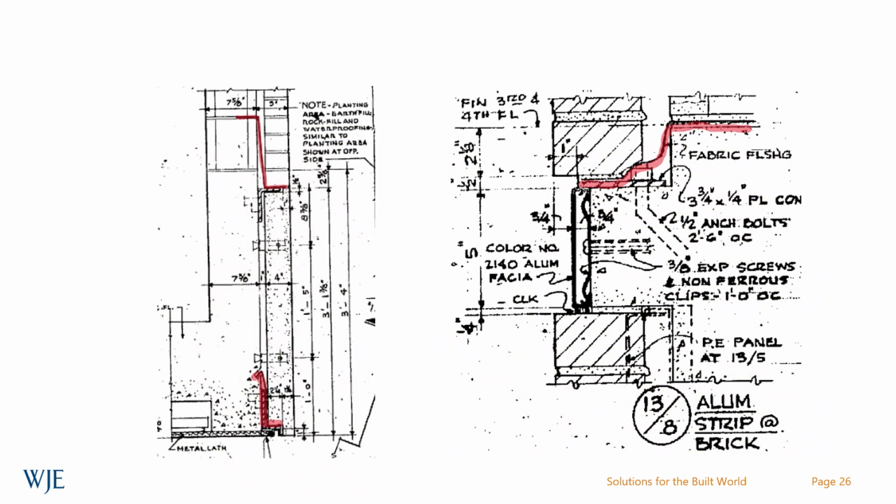Here are a couple other examples of flashings in wall systems, and you can see the flashing is not very well developed, often doesn't extend out to the face or daylighted, resulting in potential water not actually exiting the system as intended.